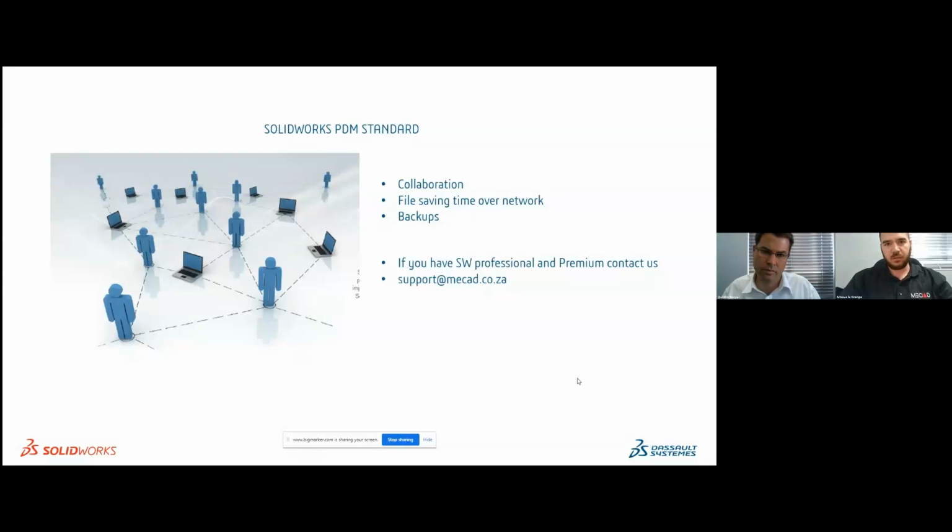Even small things like shortcuts. So in PDM 2021, you can now just do a Control-I to check in files, Control-T to do a state change. Even those small things, incrementally, if you do it over 1,000 times in a day, you can make yourself an extra cup or two of coffee without having to wait on your manager for certain information. So that's a really, really important thing for us working with PDM, again, ensuring that the files are local and not copied to the server like most companies actually do. And then they struggle with corrupt files if the network dips or anything like that.